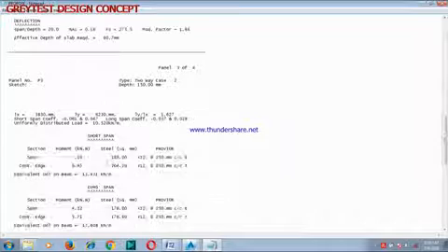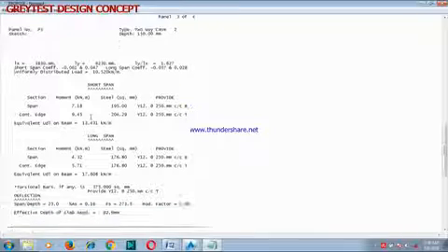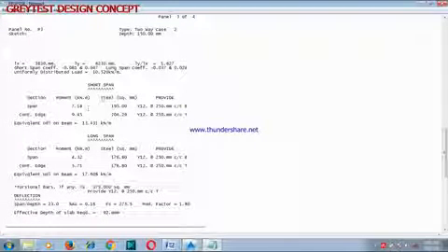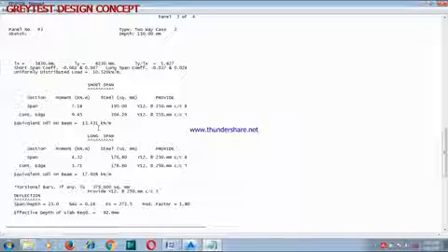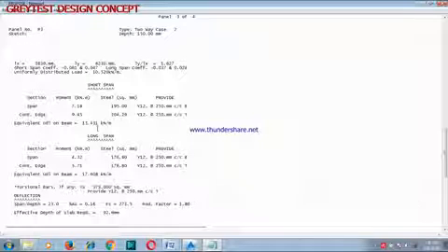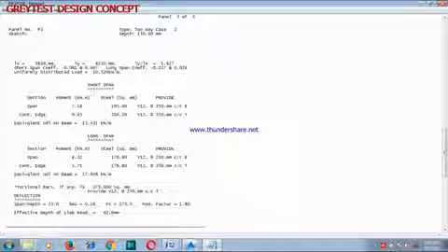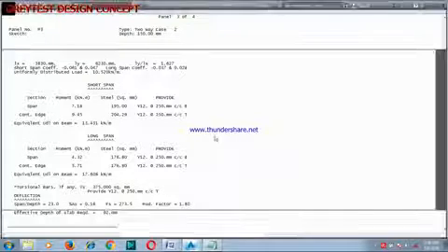Now if you come to panel 3, which is a two-way slab, you see on the short span, panel 3 and panel 1 are actually similar. They have the same width and the same breadth. Both length and breadth are the same. So the equivalent UDL on that beam is 13.43 on your short span.